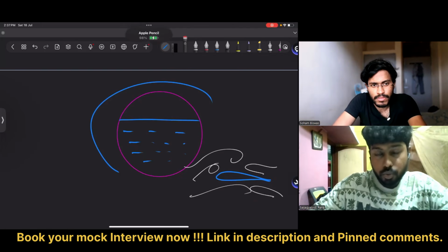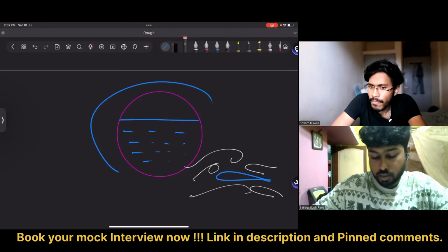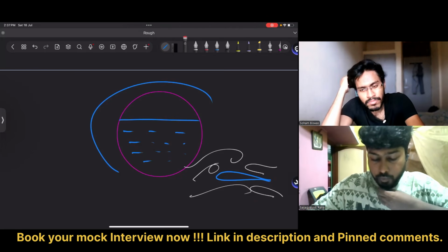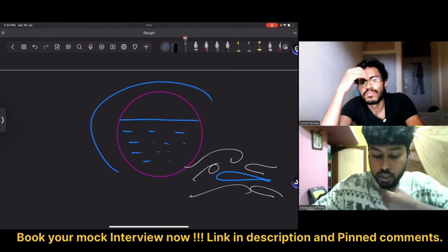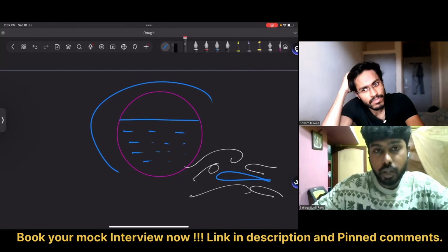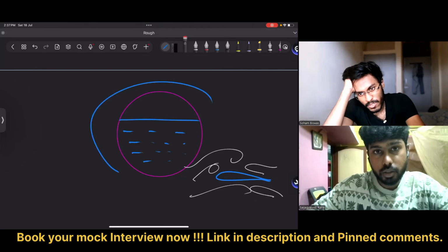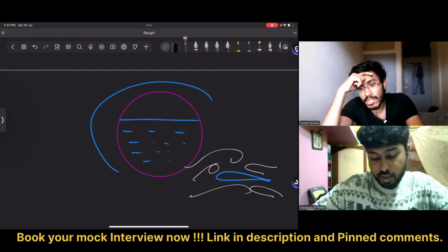Potential flow equation is used for irrotational flow, so it will be at a very high level to the aerofoil. We should use the potential equation there. And the boundary layer equation near the surface. We should use the Navier-Stokes equation because of the viscous effect near the surface.